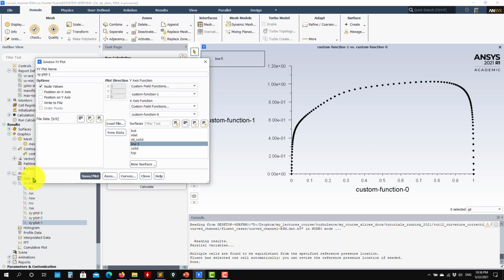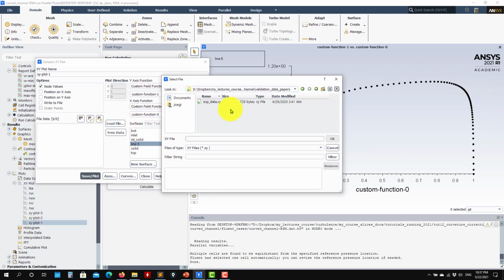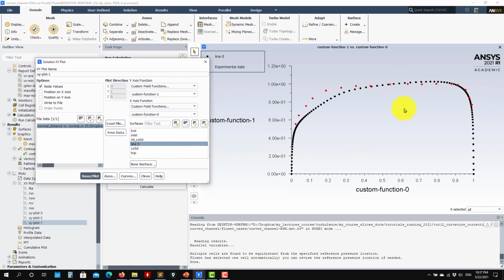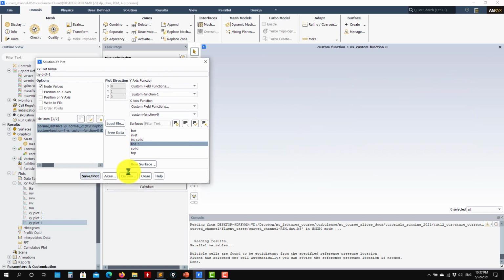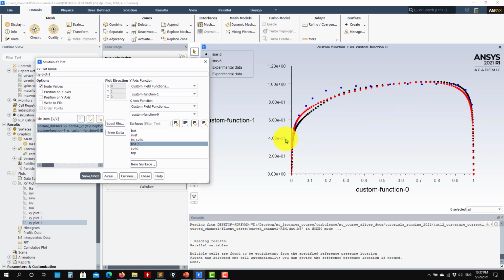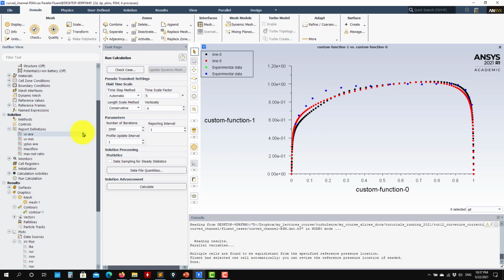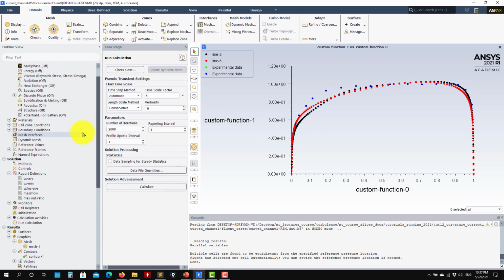And then also you have information for all the Reynolds stresses, but see here, no correction, and you can already see that you have this behavior, okay? Let me compare with the previous, no curvature correction, and voila, this is it, okay? So this is the idea of the curvature correction, and also see the influence of anisotropic models, okay? So actually, the Reynolds stress model is not that very good, at least the one that we were using, but there is an influence.